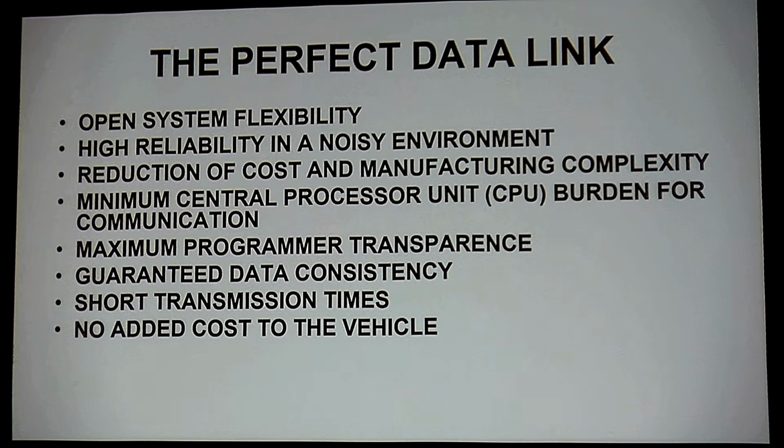The perfect gateway, well, we need open flexibility. That means I need to be able to put modules in at the dealership level, high reliability in a noisy environment, and reduction of cost for manufacturing. We don't want it high dollar. We want minimum processing. In other words, you can load these micros down by all the data they're trying to transmit, so we've got to be smart about how we're transmitting data. We need maximum program transparency, guaranteed data consistency, which is really important, short transmission times, and obviously the manufacturer doesn't want to add any cost whatsoever. So I'm going to have to weigh these out, and it's always going to be a pick and choose, right?